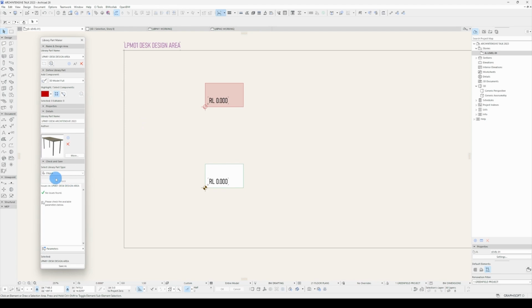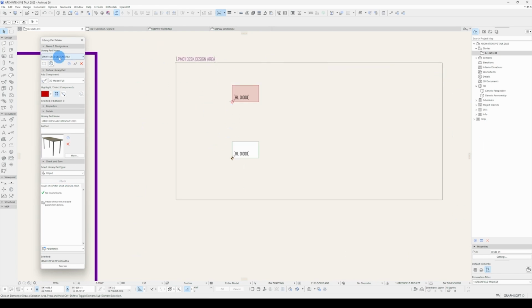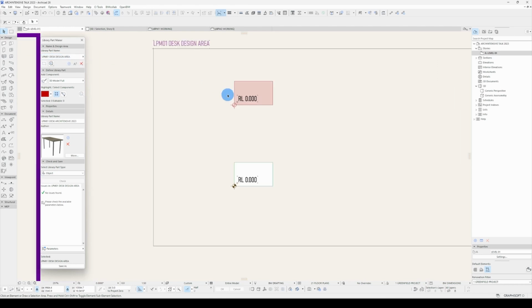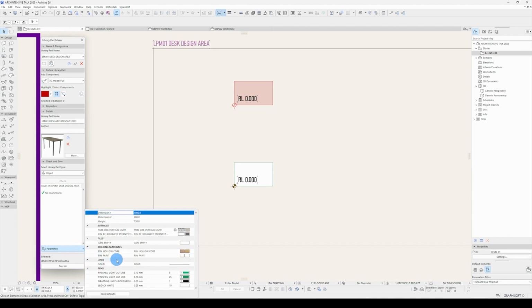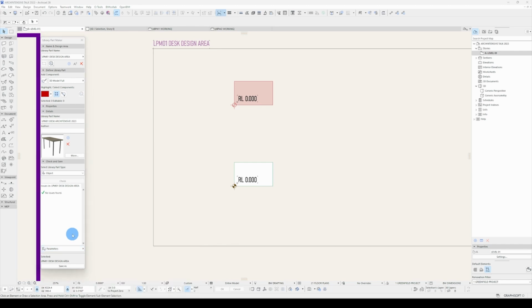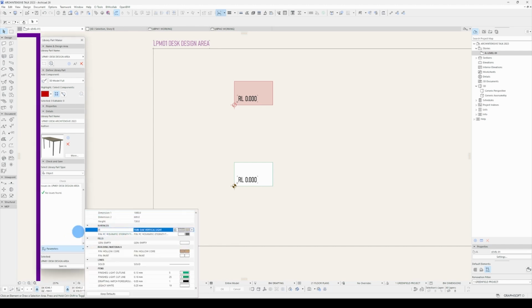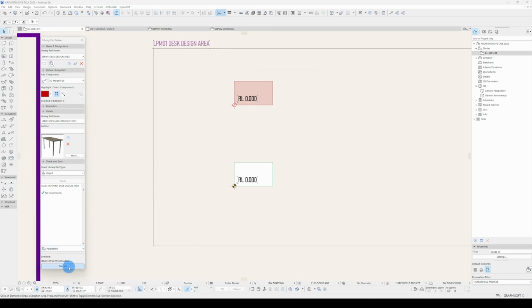So I'll check it, and what that will do is go through the entire design area for this part that I've defined and make sure that what I have put in here has been assigned and it works. And you can see here, no issues found. At this time, I can also rename the parameters like I did in the Save As method. Save As.